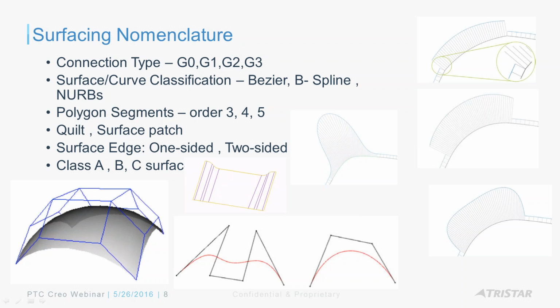whenever, like you can see in those images there, when you have two curves that's sharing a common point, right? We call it G0. So essentially, a surface created through those two curves creates two patches. However, what about the continuity, right? You don't have tangency, right? So that's G0 continuity, but sometimes, most of the times you do need tangency, right?